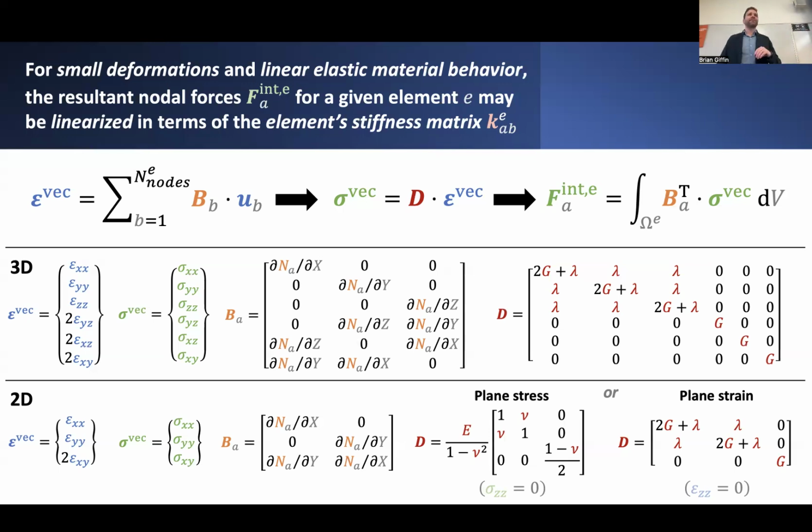And then from that description of stress, we could also finally note that the expression in the integrand of this internal force computation can be rewritten conveniently as involving this strain displacement operator B, just by taking its transpose. So B transpose dotted with the vector of all these resulting stress components turned out to be equivalent to the integrand of that preceding expression we had on the last slide.